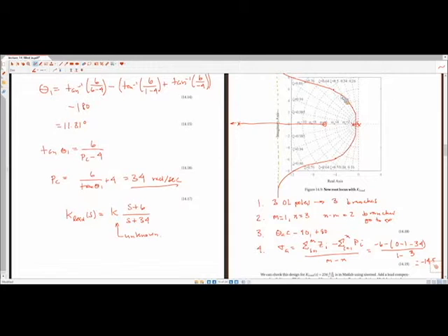All right. So now we've basically changed the shape to make sure it goes through this point, and now we want to directly place the pole at this location. Before, if we go back a few lectures, we calculated a value of k such that the closed loop poles lie exactly on the imaginary axis to understand stability. How did we do that? What tools did we use there? Yes, Justin.